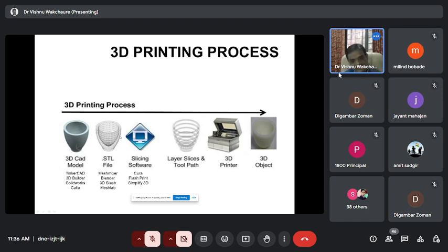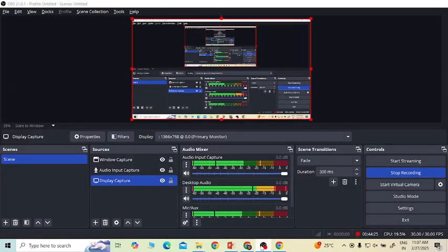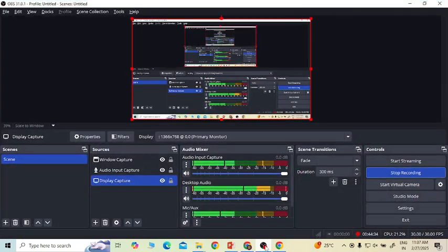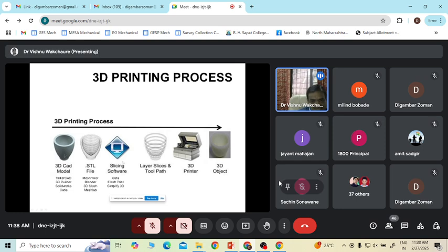Here you can see it is discretized, divided into small portions, basically layers, in the form of triangular elements. Whenever you create the model, you have to save, say for example, a .part file. Similarly, if you go to File, Save As, you will have a number of options for what format you want to save that CAD model in. It could be neutral file formats like IGS, or a STEP format, or the .stl file is another option. If you have to use that model for 3D printing, you have to use this option to save those files. Once these .stl files are created, they will be sent to the slicing software.